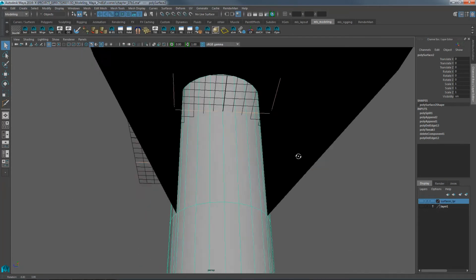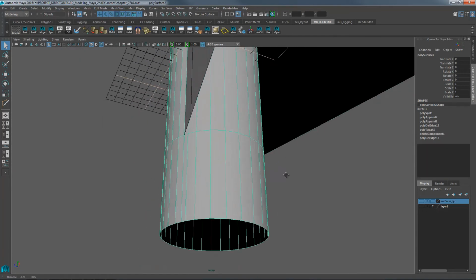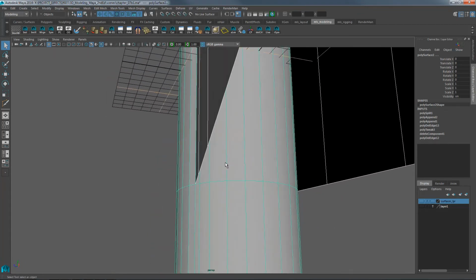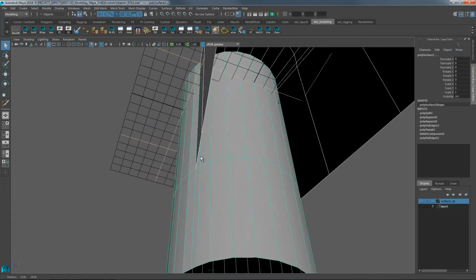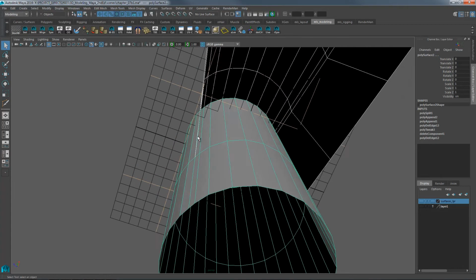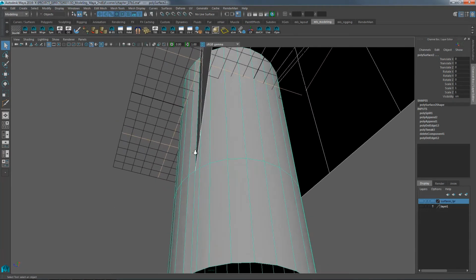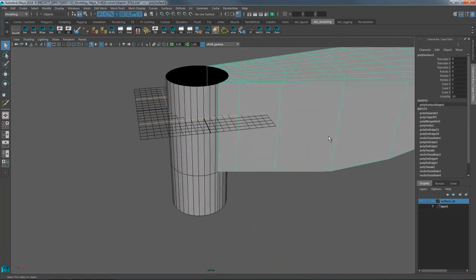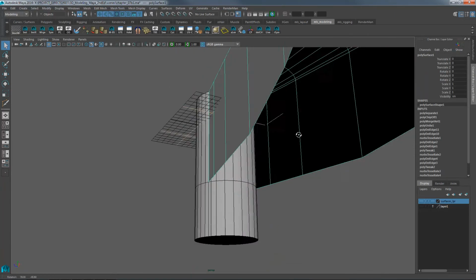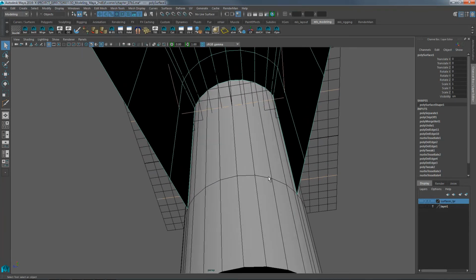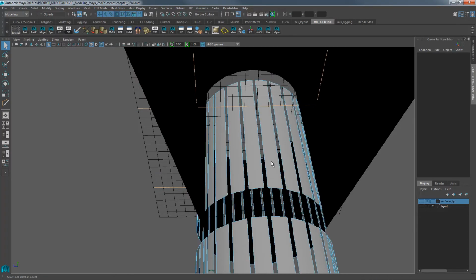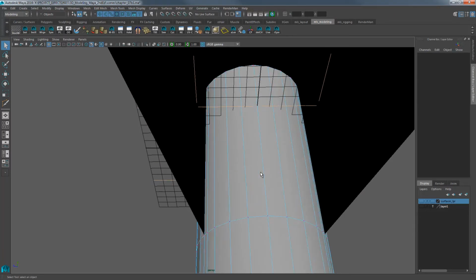So we still don't quite have it yet, right? Because if I were to stay just the way I am and combine these things, it's basically the same as having a non-manifold mesh, just like a strip of polygons extruded off of an edge. That's not good enough. What I really need to do is thicken this piece, and then at the boundary where the thickened part matches, extrude this section. So let's start with the extrusion so you can see what I'm talking about in profile.